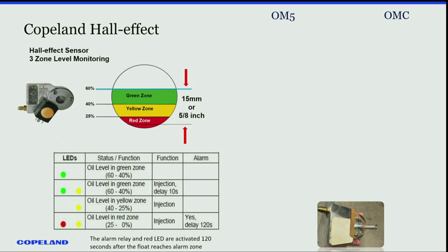There's also a tube that is connected to these. Some are already connected, some you've got to screw on there, because there's an adapter that goes from the oil control adapter into the compressor. So when it feeds, you want to put that adapter in there to make sure that oil gets out into the crank of the compressor.